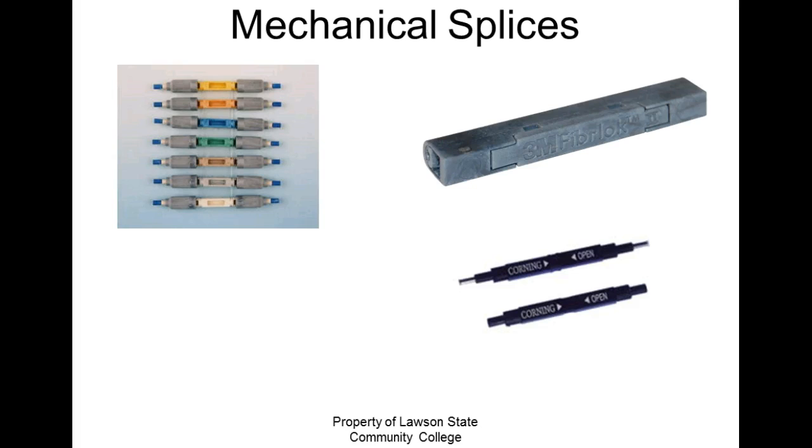It's got the procedure on the actual splicer itself. And then when you crimp this thing down right here, that sucker's permanent, right? Does that make sense? If you needed to remove a permanent splice, you're going to have to cut it out. If it's a semi-permanent splice, you can just unlock it and pull it out.